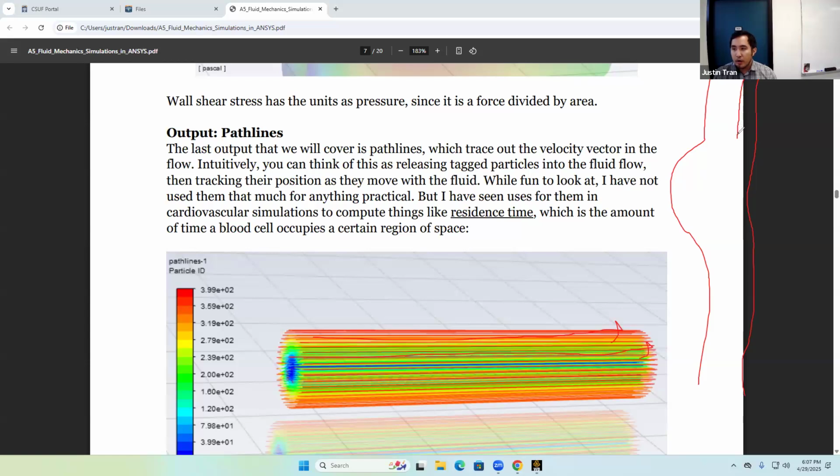The fluid is going to want to fill that space, but it may not do so efficiently. It may try to round this corner. You may have a pocket of recirculating flow within that aneurysm itself. A pattern like that is something that you can view with the path lines, and it may indicate something like flow stagnation, or residence time of the fluid in that area.